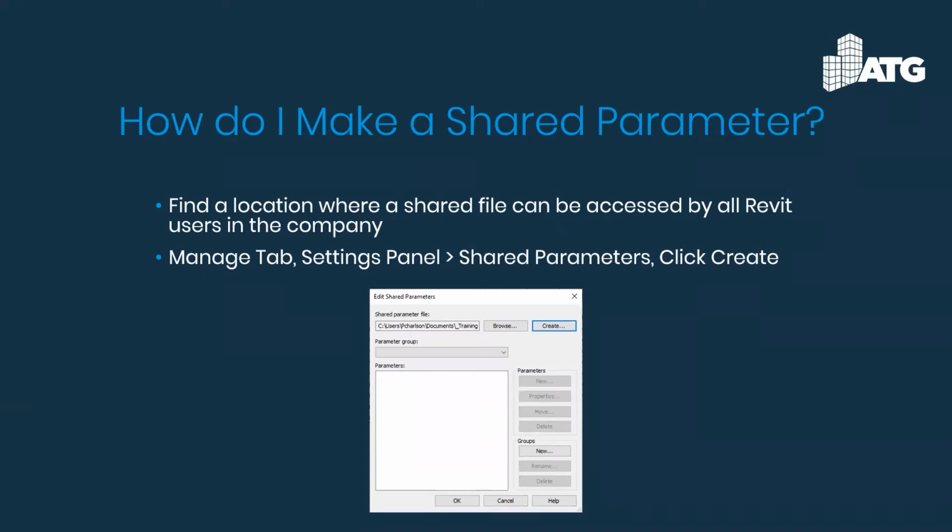If you do want to start utilizing the shared parameter and modifying it, again, you probably want to check with the BIM manager to see what kind of access you can get with it, and maybe get a little bit more internal discussion about the shared parameter. Now, with that, you'll find the shared parameters in your Manage tab,